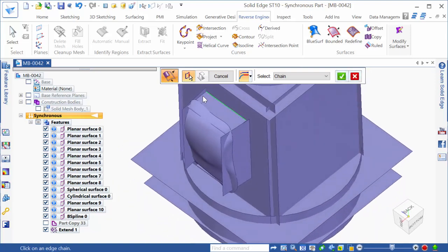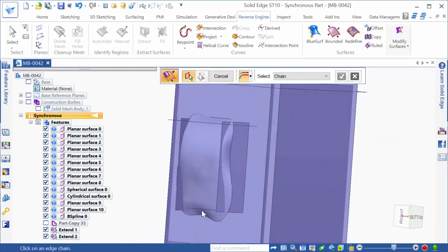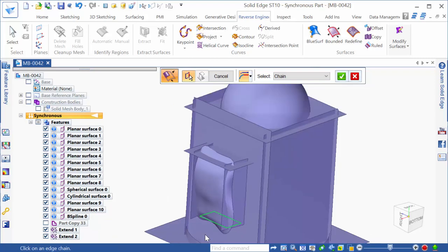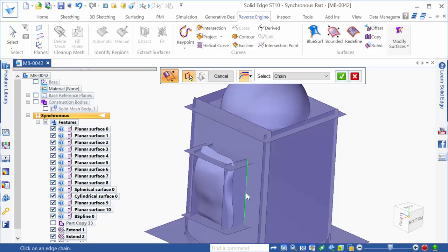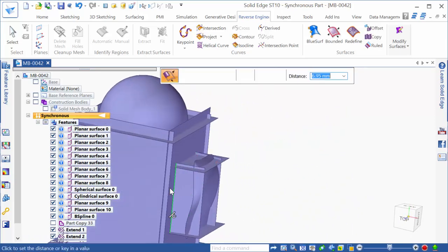So we want to make sure that these planes all are intersecting, and depending on what your first selection is, that's going to show the direction you need to drag out, right? So my first selection was this inside face, or this inside edge, so I drag outward to make it larger. And then down here, I'm going to pick up this outside edge because that one's much easier to see. You can select through the part, then drag outward, right? You don't have to drag inward, drag outward so that everything intersects. And then we can do the same thing with this edge, just push it into the middle just to make sure that everything is intersecting. And we'll do the same on the other side.